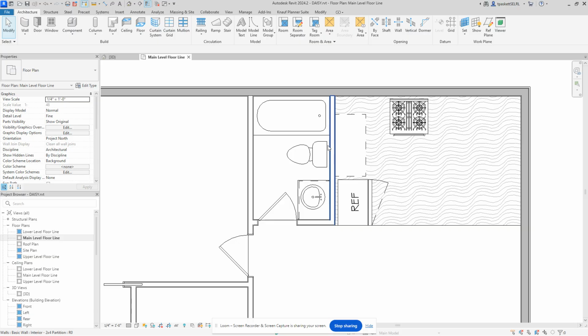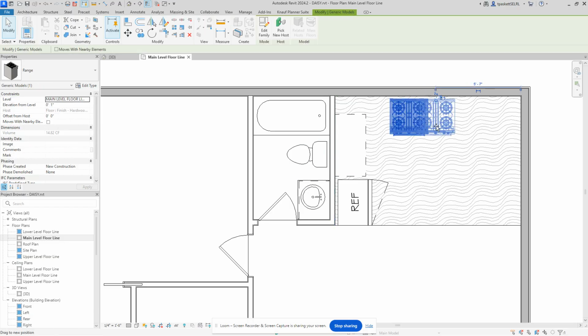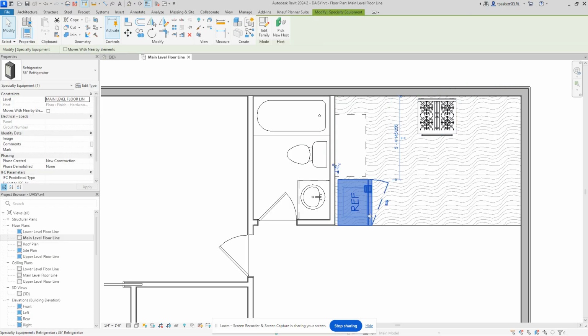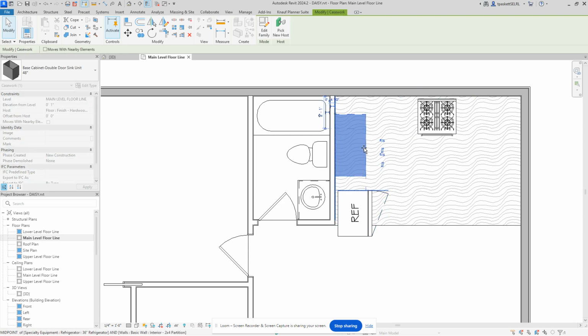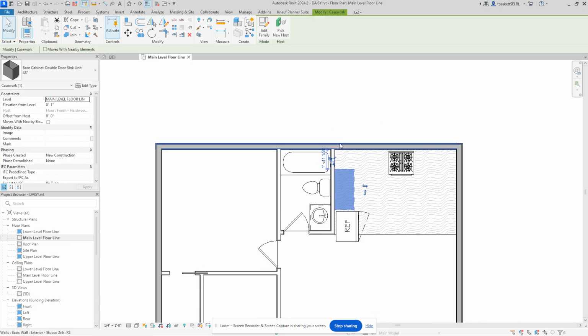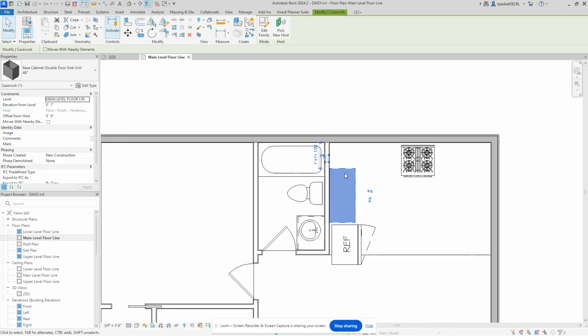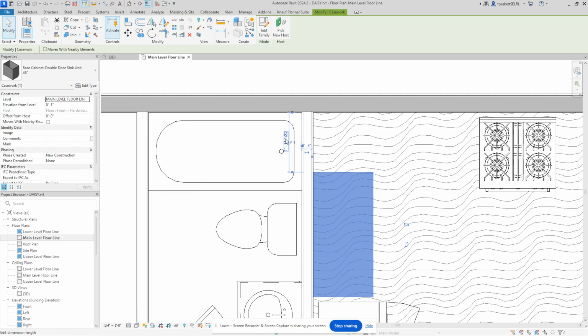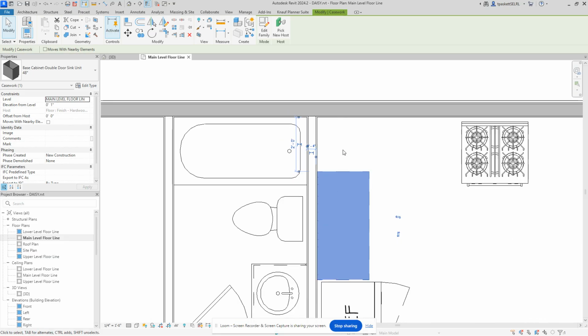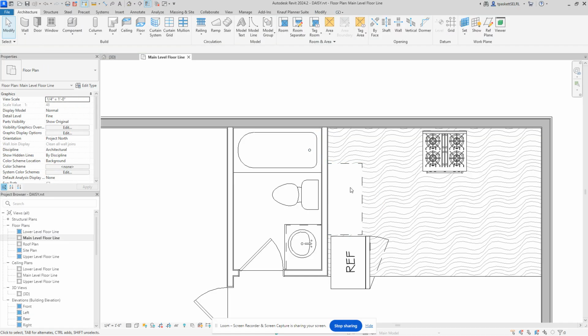Okay, so I'm going to move my stove apart a little bit here. Move that over there. I'm also going to move the refrigerator out a little bit because I need the 2-foot space. Technically, at this point I'd tell the kids to pop this kitchen out and put a wing on the house to make it a little bigger, but we're not going to do that. I need this distance from the wall to the cabinet to be 2 feet, because this is where your other cabinets will go.